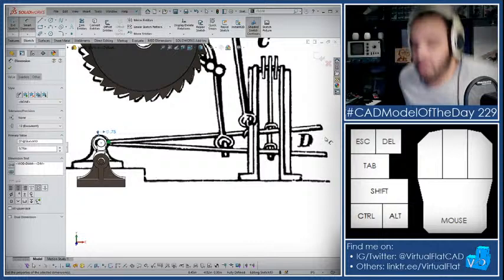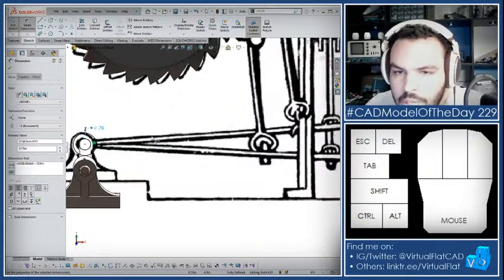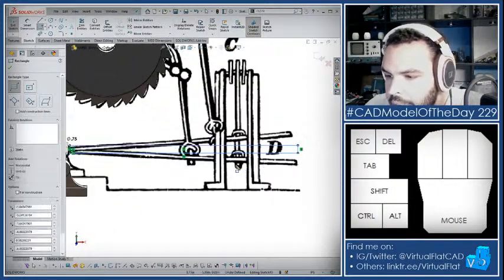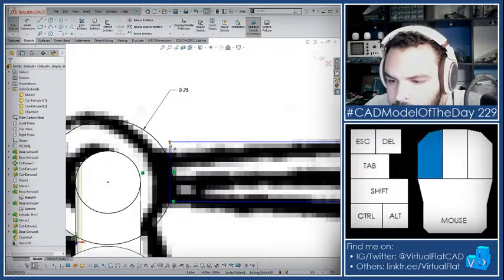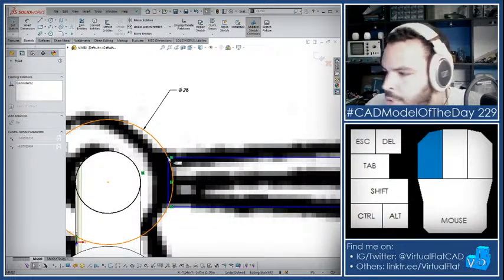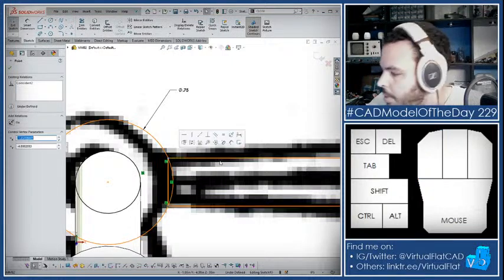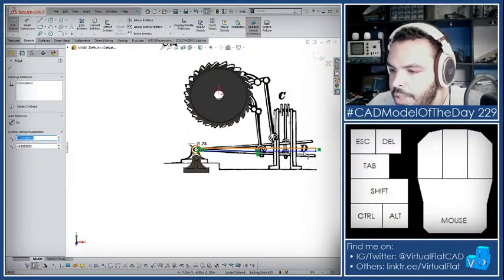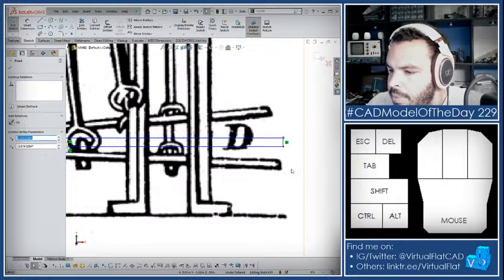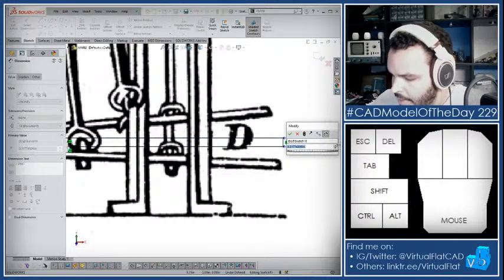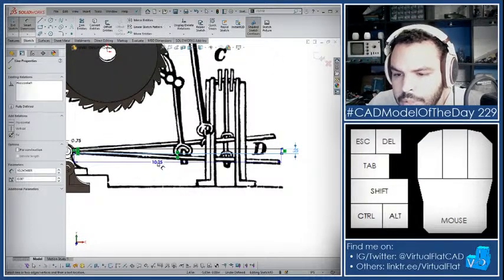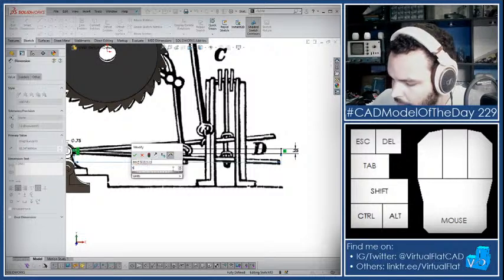Alright, just going to adjust my seat. Yeah, let's do that. I think the easiest way is to get a corner rectangle. Start from right here, go all the way over here. Snap those. Just by virtue of those 2 points being on the circle, it's automatically centered, which I think is pretty cool. So you don't have to add any additional constraints. Now it's just a matter of making these about the same thickness as what it looks like in the picture. So like a quarter of an inch flat bar. That's kind of reasonable, I guess. And 10 1/4. All right.